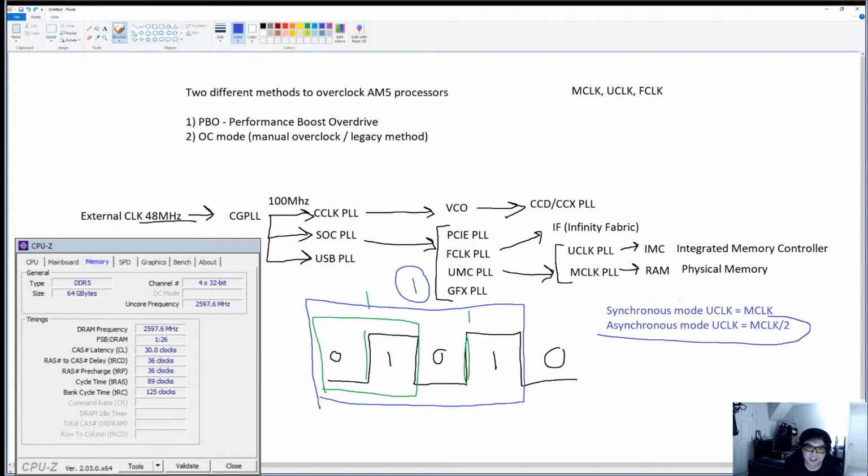But the reason why this exists is because if you're trying to overclock memory or push high frequency RAM, the IMC is going to be the limiting factor. In my experience with both Intel and AMD, the IMC has always been the limiting factor when it comes to memory overclocking. Almost never have I been limited by the actual RAM itself. Now, granted, that's because I'm buying RAM that I know is the right type of die. In the case of what I'm using, I have Hynix memory in here right now.